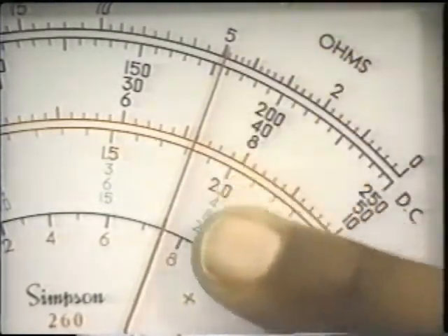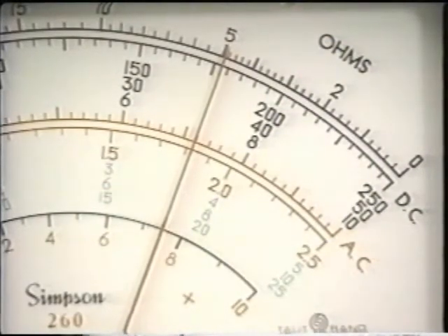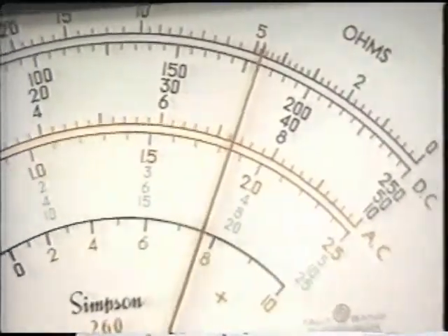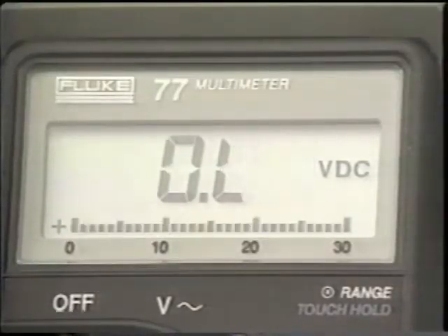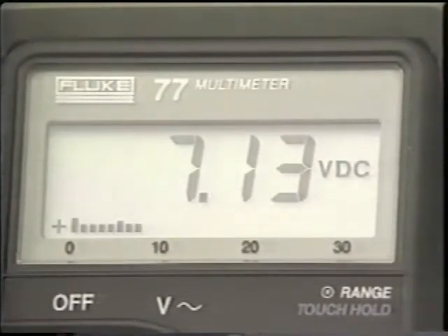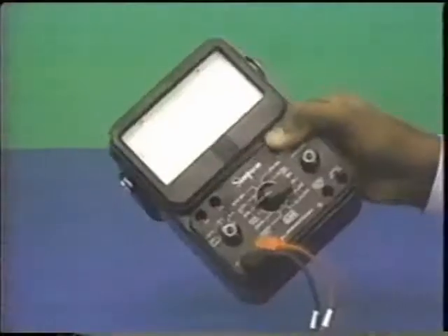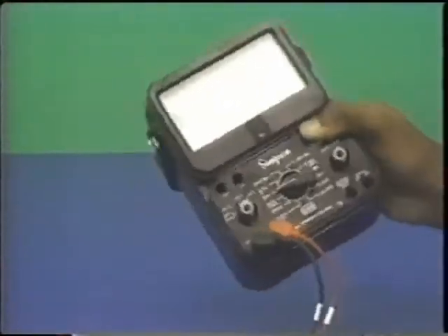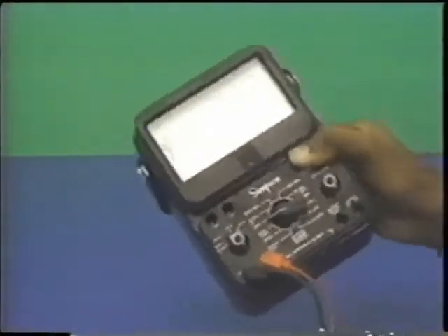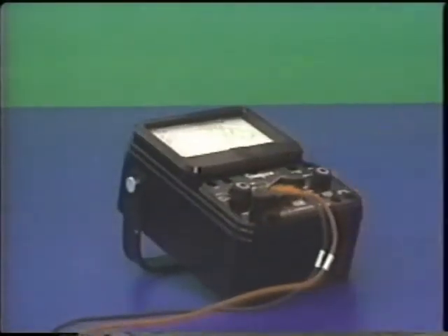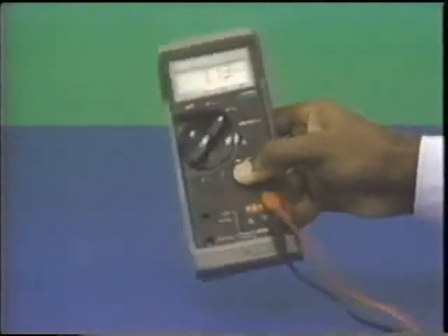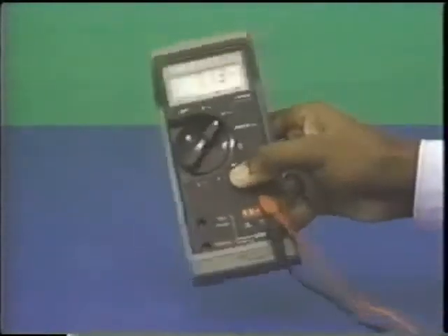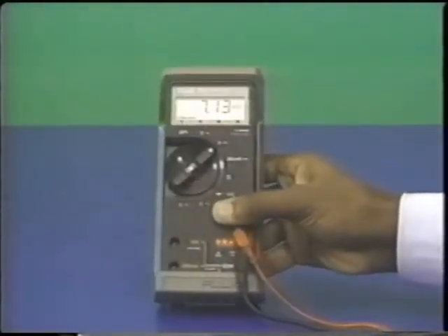Another difference is that there is a larger margin for error when using the analog type. An error can be made by choosing the wrong scale to read, or by viewing the meter face at an angle. The digital display allows less room for error by showing the exact value without your having to interpret a scale. Analog multimeters are sensitive to vibration and are affected by the angle at which they're held. For this reason, the analog type is popular in the shop where it can be placed on a steady, level surface. The digital type is not affected by vibration or the angle at which it's held. Therefore, the digital multimeter is popular in field service applications.